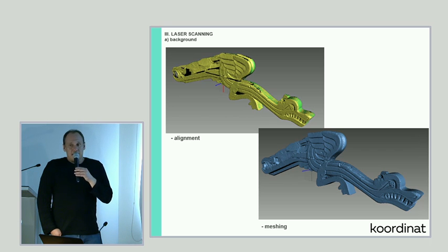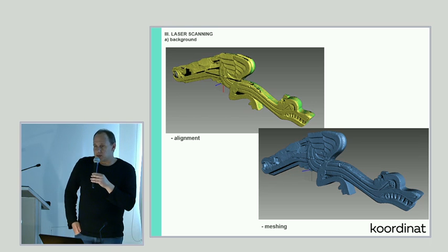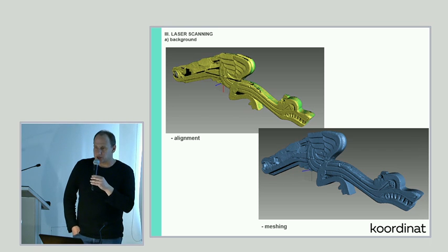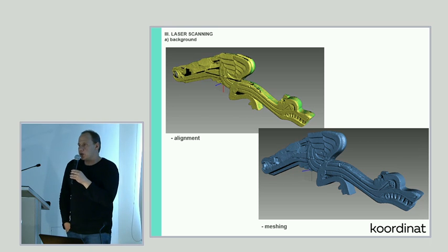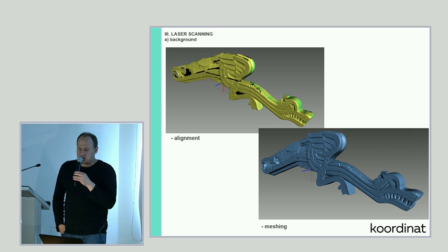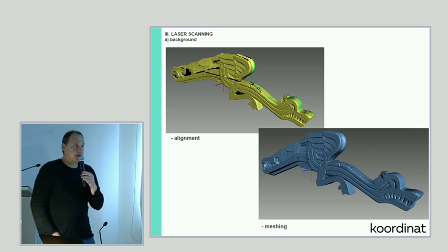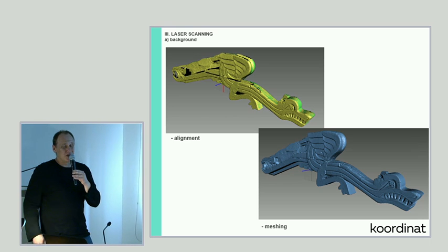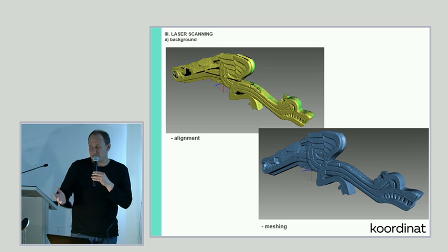for doing architecture. I have one phase-based scanner, which is simply faster, but good for operating at short distances, and one pulse-based scanner, which I use outside because it's a little bit slower but has a greater range, and it also has all the characteristics of a total station, so I don't need to register the scans together.